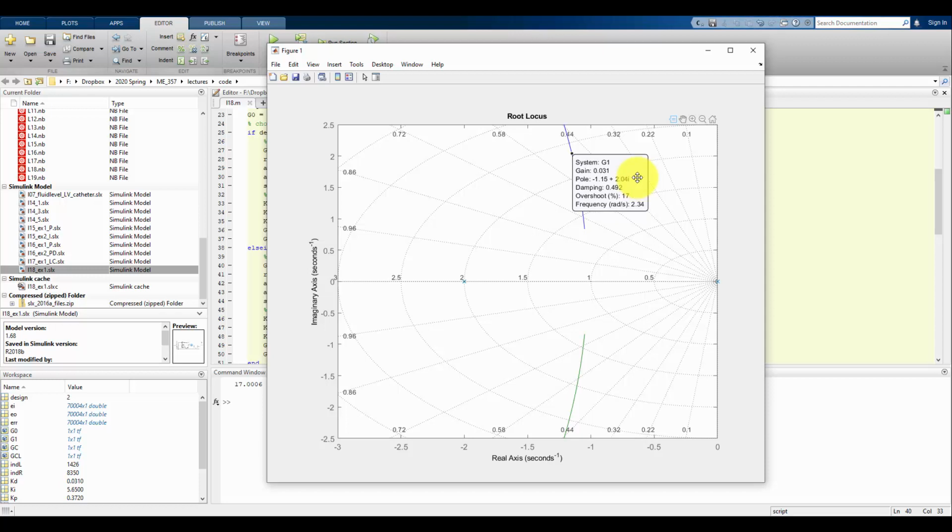So if I used a little bit higher gain or a little bit lower gain, it's not a big deal. It's not going to change it too much. And with some of the rounding, like using only 3 digits for that b value, I'm not going to get exactly the desired pole location, but I mean, I'm pretty close here. So this being the closest pole, this is saying use a gain of 0.031.